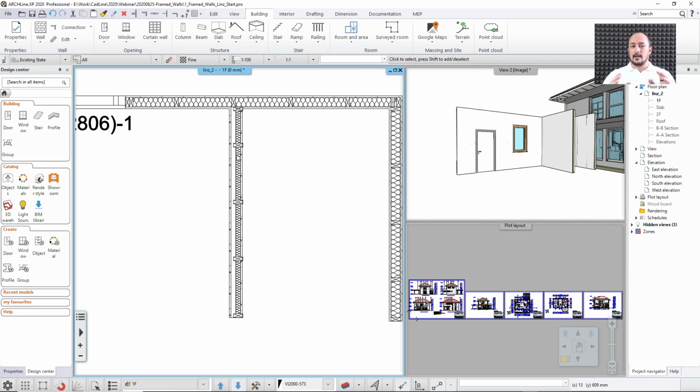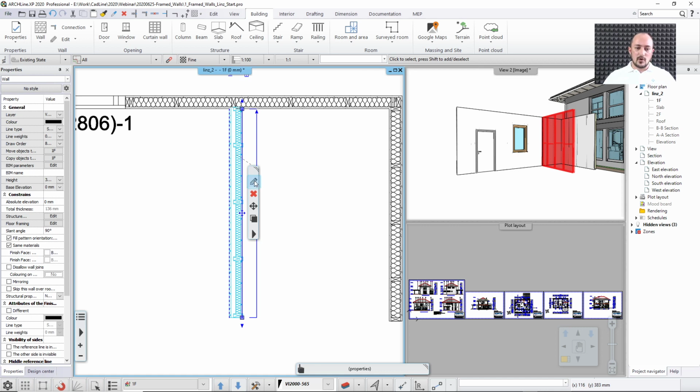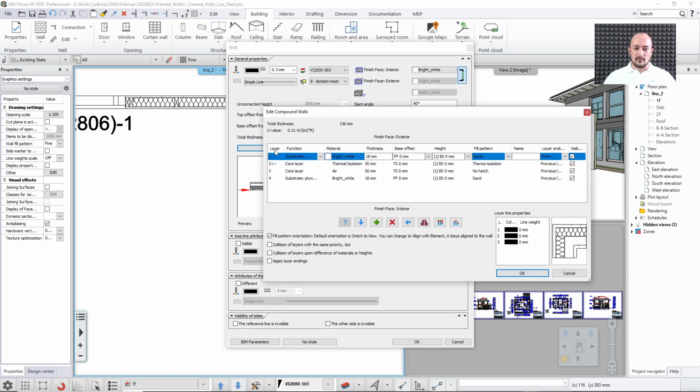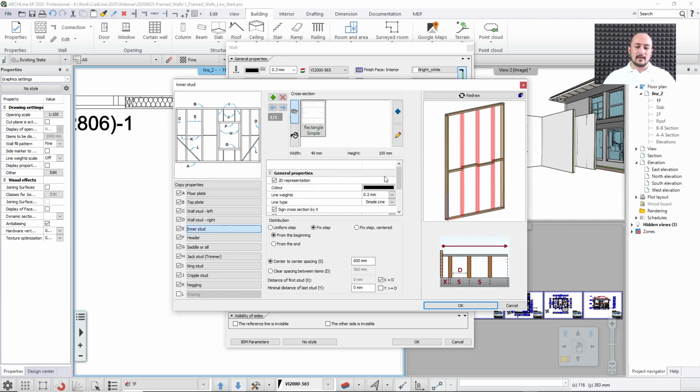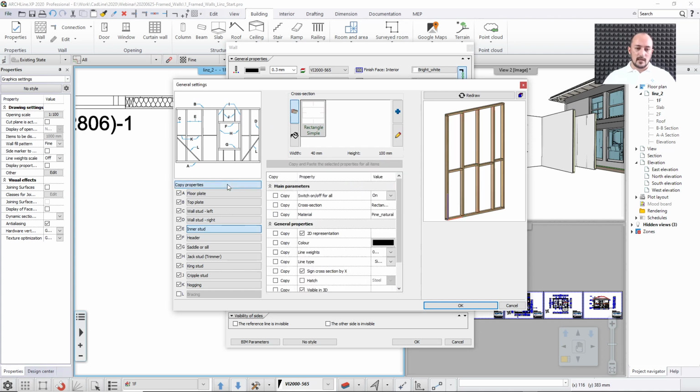Now again, the framing jumped to the first core layer because that is the indicated layer. Unfortunately, you cannot go here and say that you have two indicated layers. That would make no sense. But what you can do is solve this at the framing level. The framing can have something we call an offset.